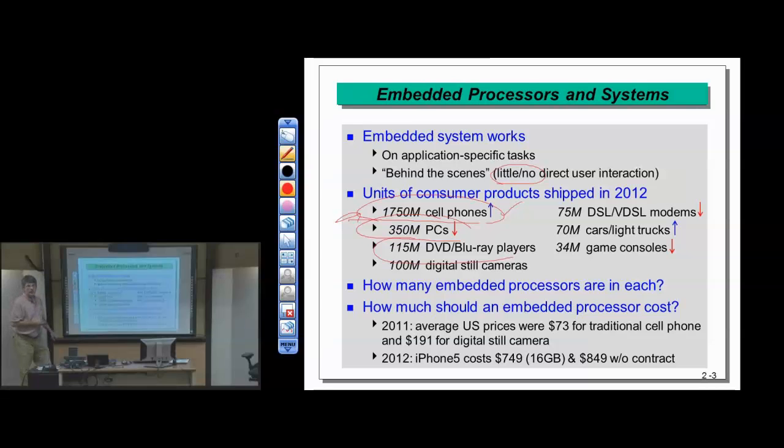Wi-Fi cards. Initially these generations of peripheral control and interfaces will have programmable components on them just to get to market faster. But with each generation, it can be more and more hardware to reduce cost, reduce power, reduce physical size. Eventually, after 3 or 4 generations, the programmable core has been replaced with mostly dedicated hardware, just for savings. Integration basically just down to one chip as much as possible instead of multiple chips. So these days, Wi-Fi controllers are going to be mostly hardware.